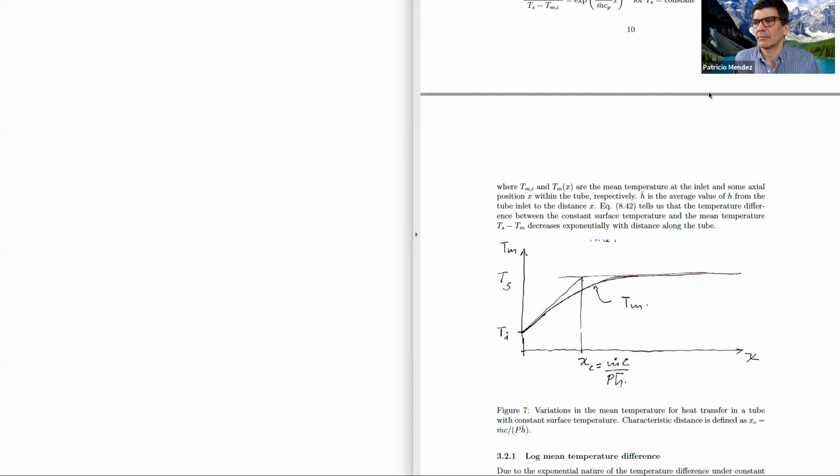In this case, we also see, in the case of a constant tube temperature, that as the fluid goes down the pipe, the temperature difference between fluid and pipe gets reduced to be essentially zero, and we would have no heat transfer here. We pay the same money for a piece of tube in this region of the heat exchanger as for this other region of the heat exchanger.